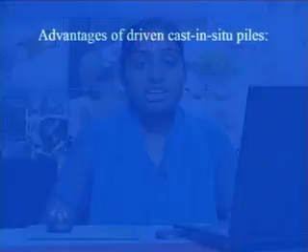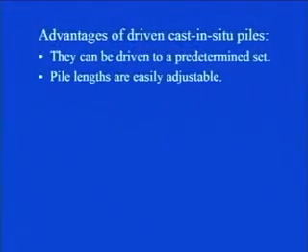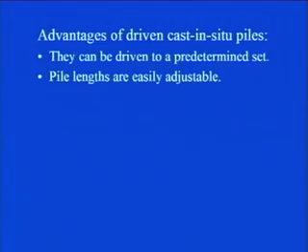First, starting with advantages of driven cast in situ piles. Once again I would like to recapitulate what these words mean. Driven means you are driving it by any mechanical means, by hammering or by vibration. Cast in situ means it is being cast at the site itself. They can be driven to a predetermined set. Pile lengths are easily adjustable since they are being cast at site only.